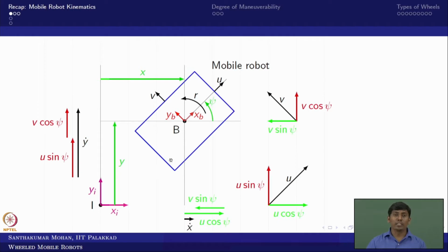But these generalized coordinates are dependent on the input command, which we call the velocity input command, or simply the body-fixed velocity at an instantaneous time. So u, v, r are the cause of motion for this particular motion. Based on this we derived the relationship, because we cannot bring this u, v, r directly into the position domain. Instead, we elevated x into x dot, y into y dot, and psi into psi dot. This relationship we obtained here.